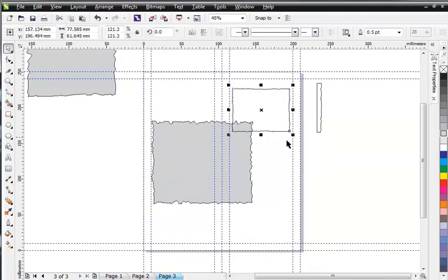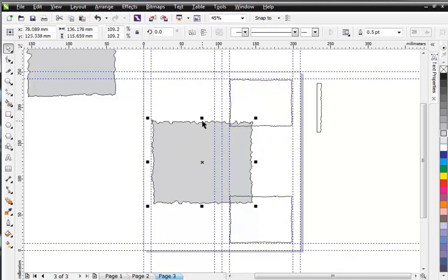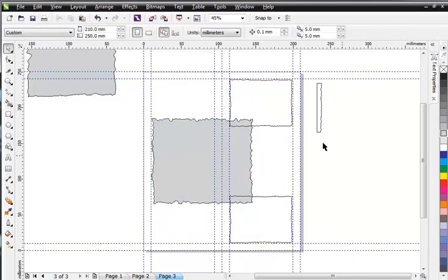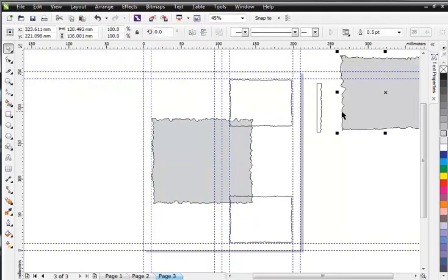Press Shift and F4. Upscale this figure a little bit. Hold Ctrl, drag the figure down, keep holding the left mouse button and press the right one at the same time. This way we've duplicated this figure and placed it at the bottom of the catalogue page. Let's say that this part is ready now. So we now know a couple of techniques in which we can create such a figure.